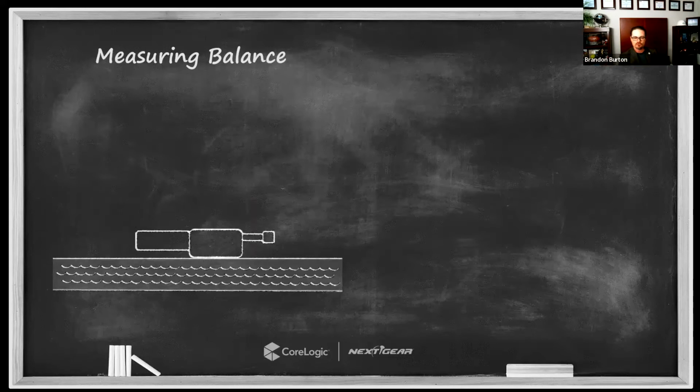So in episode 2, we talked a little bit about the use of hygrometers on the surface of materials. And there are 2 different types of hygrometer measurements that you may take near a surface. I want to be really, really clear on the difference between these 2. In one measurement, we're simply placing the hygrometer near the surface. Okay, just near the surface. No other special measures are being taken. No plastic is being used. We're not covering anything. We're just placing the hygrometer near the surface. And what we're trying to measure is the humidity at the surface during the active drying process.